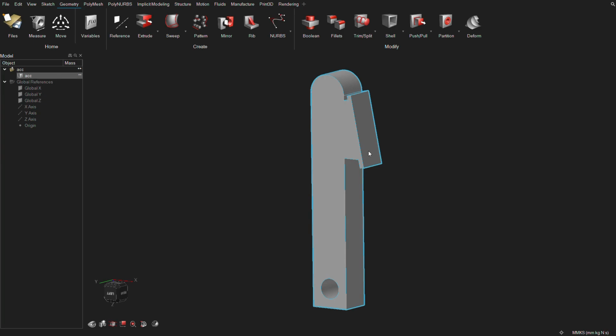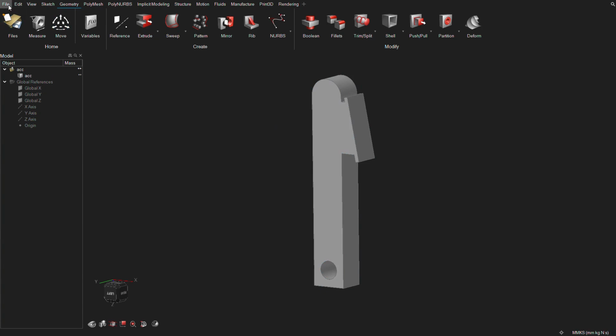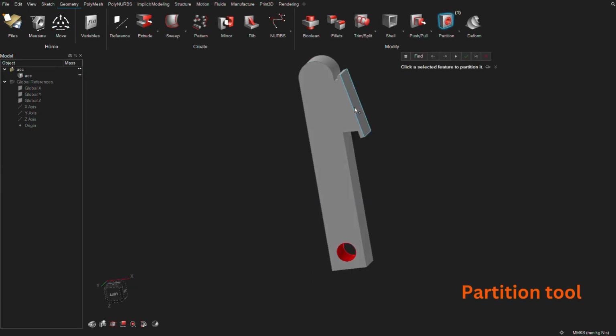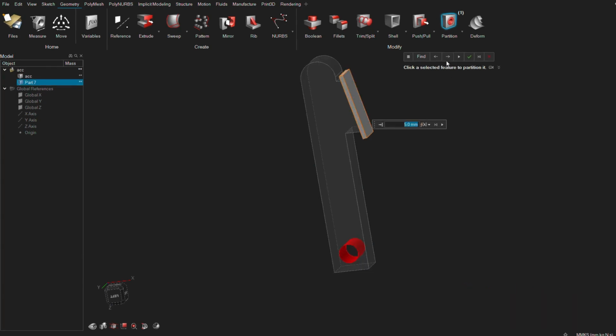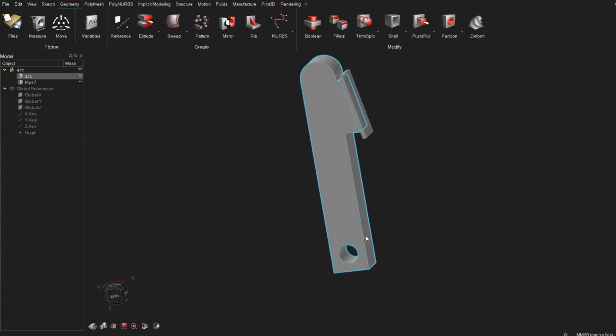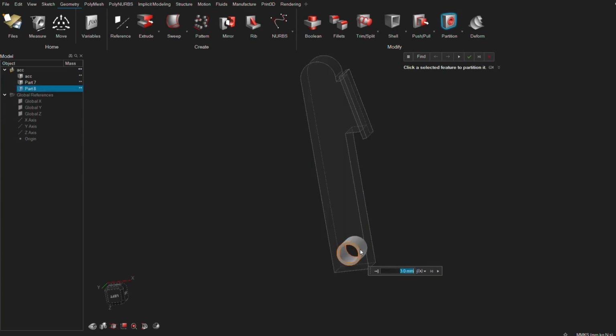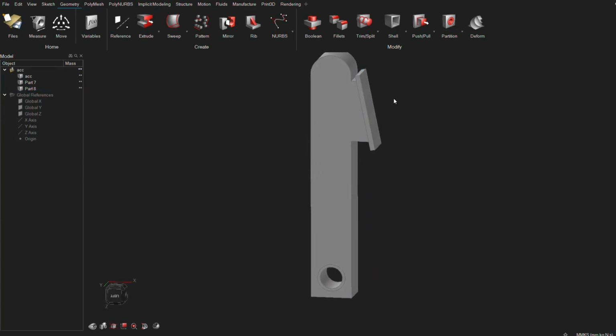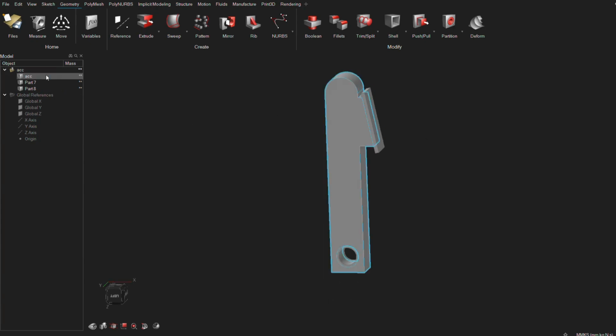First, we have both pedals, accelerator pedal and brake pedal, to optimize. So let's start with the accelerator pedal here. Let me partition the model for application of our boundary conditions. It should be a 5 mm top plate and then a bottom cylinder of 3 mm. Okay, now our partitions have been set.